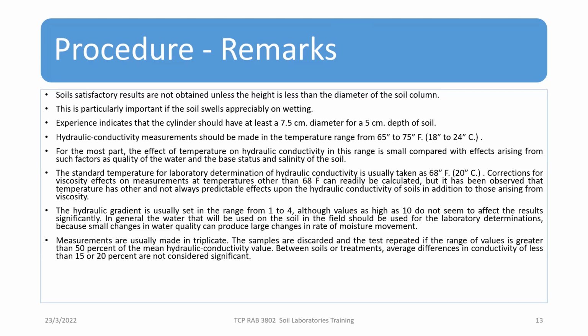Measurement is always made in triplicate. The samples are discarded and the test repeated if the range of values is greater than 50% of the mean hydraulic conductivity.